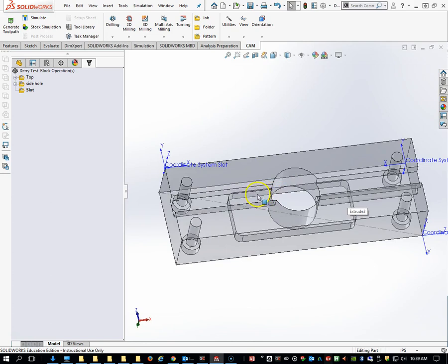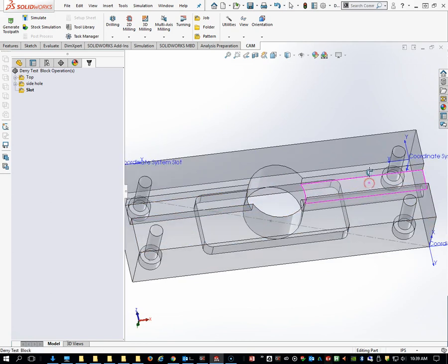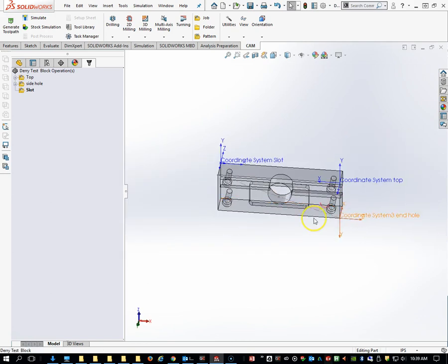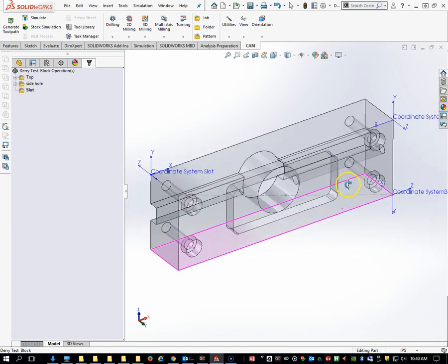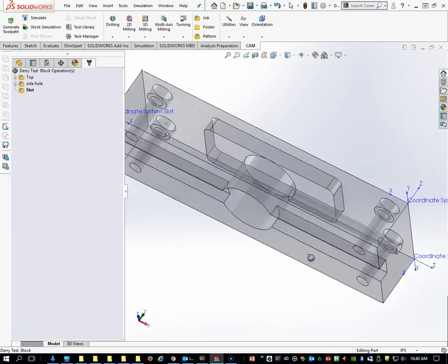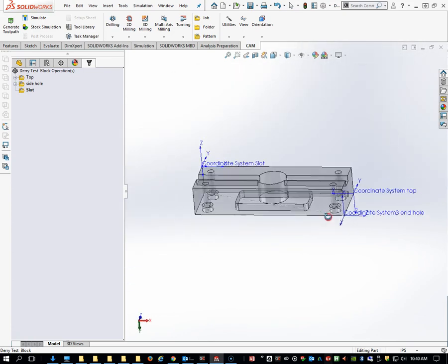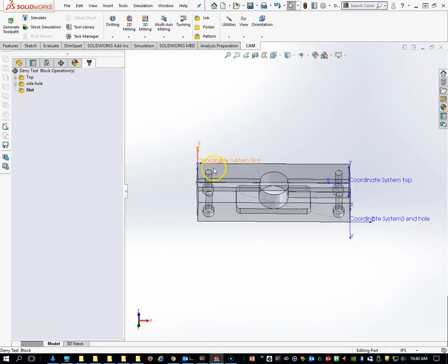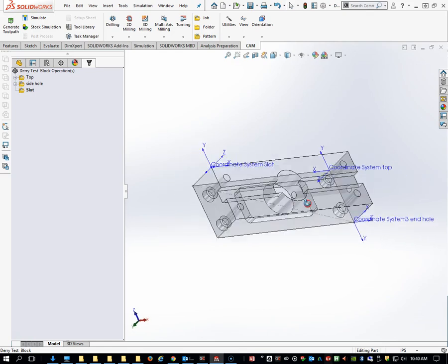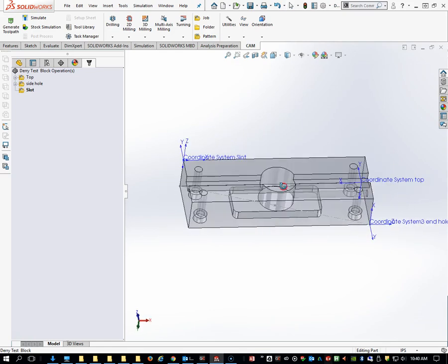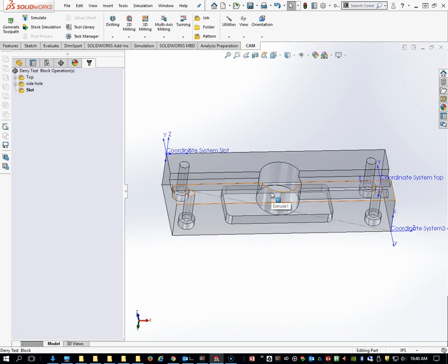I've been experimenting, and it turns out that the existing geometry is not going to give us the option of using the slot command. So we're going to need to create some new sketches, or a new sketch, in order to use the slot command as it's intended. So this is something that you should know how to do. It's not uncommon that the model doesn't contain the geometry that we need. Sometimes it's a workaround if we want to make tabs.